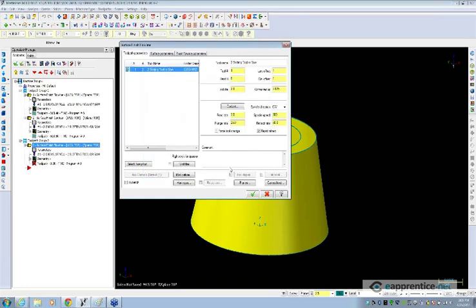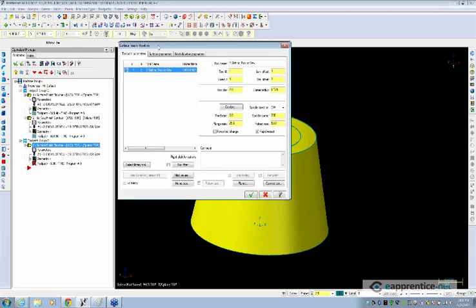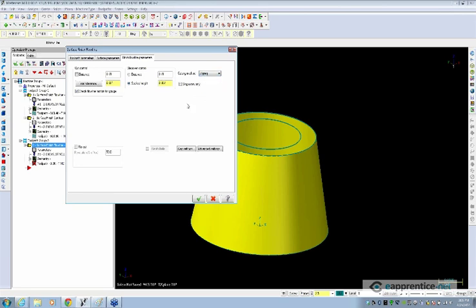The other type that will do it is a lollipop end mill, but you're limited in the amount of degrees that you can go underneath the surface. So we've got our tool selected, surface parameters, we're starting up above the piece at 4 inches. It's like 2.5 inches high, retracting to 3 inches absolute. I'm going to start with the default settings so you can kind of see what you're going to do here.